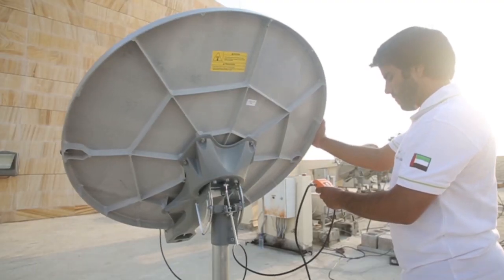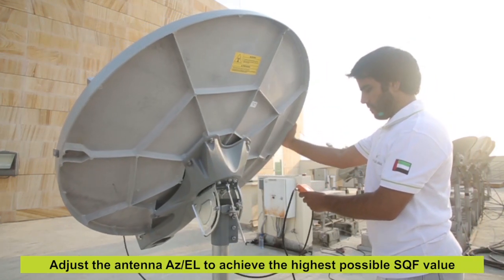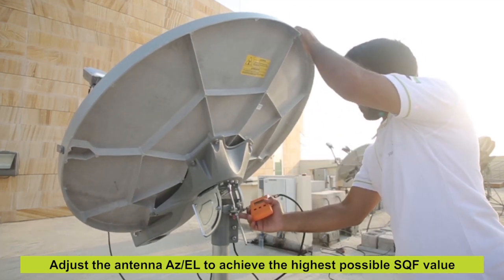It is advisable to set the elevation angle as displayed on the modem page and start sweeping within the azimuth range. The elevation angle is to be adjusted only if no signal was received.